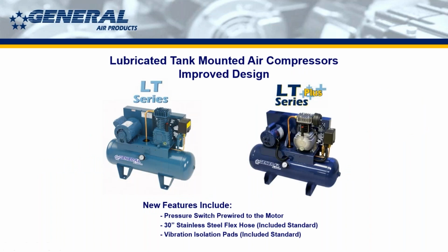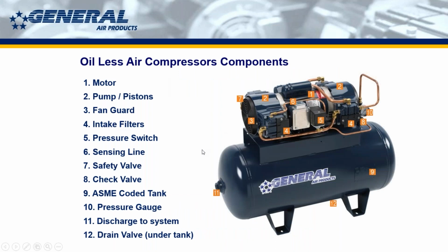We did do a design upgrade. The biggest part of the upgrade, and this was several years ago, but I still like to bring it up because some people don't know. You notice this line here going from the pressure switch to the motor. We used to have you do that wiring yourselves, but now we've been able to change that so that we pre-wire the motor to the pressure switch. That's the biggest one. Then we included the flex hose and vibration pads and things like that. But that's what our LT Plus series is.